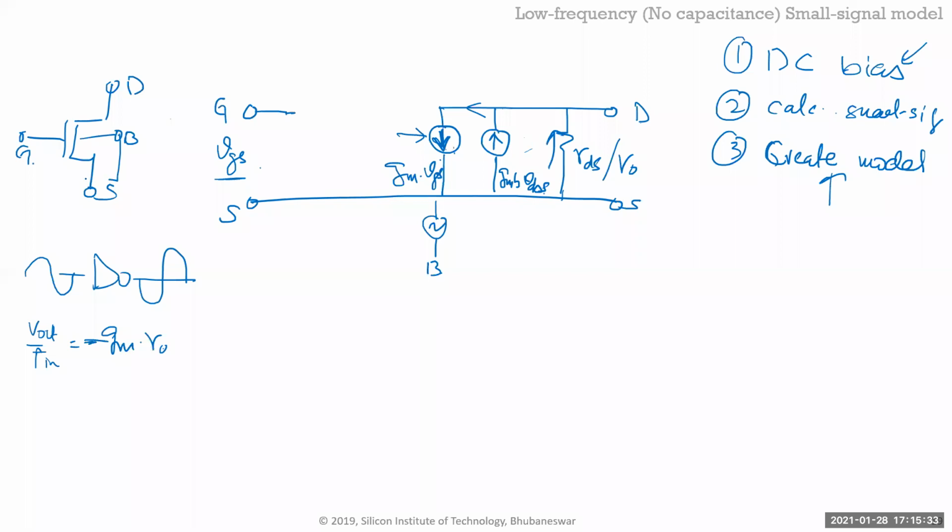So let's say, in that inverter circuit, those bulk and sources were shorted, right? Which means that there is no VBS, so you can actually take this off. So in most small signals, all you're doing is taking the GM and R naught, okay? And if you took the GM R naught and let's say the load was just a current source, then it's minus GM R naught. So all it's saying is that if your voltage is increasing, your output is actually decreasing. Or in other words, it's telling you the phase of the signal. So the phase is inverted.